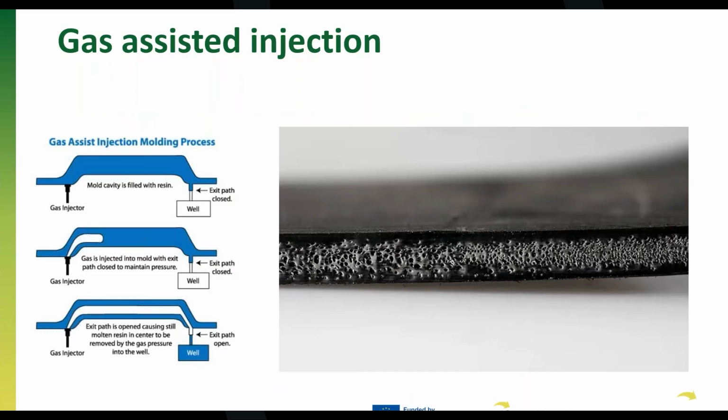I started to go into different technologies that we can use in both cases, fossil-based and bio-based. One of them is gas-assisted injection, in which we have physical and chemical gases that can be explored. Usually with bio-based materials, I have seen more the case of the chemical ones. That doesn't mean that we cannot go physical, but the entrance of this gas into the mold means high forces that can degrade the material.